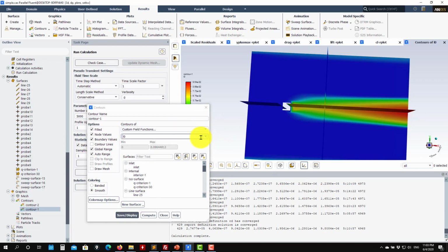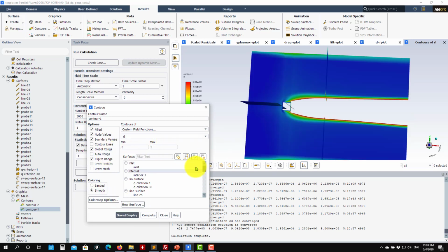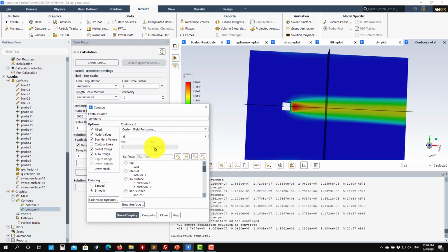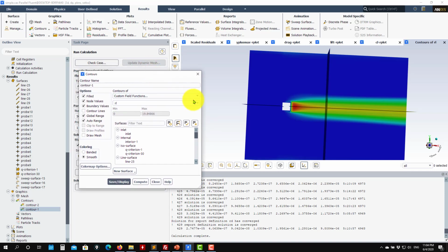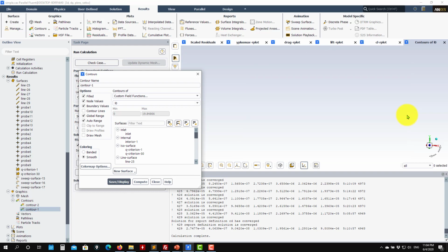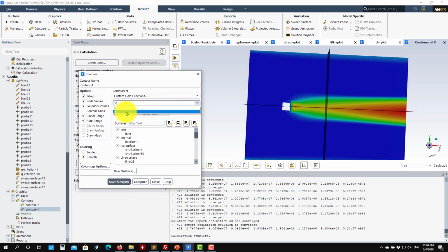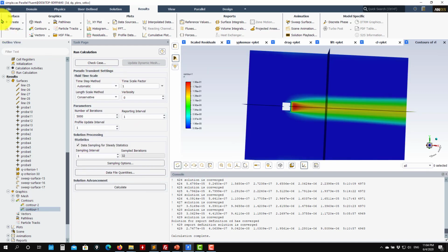So our integral length scales, and then we go RL and outer range. And as you recall the previous mesh, you will see that this probably is much better. Okay, the RL limits, let me erase this one. It was up to 8, I recall, or 10. Look here that we have larger values. Okay, it's telling me that we have much better resolution in many areas. And the integral length scales, well, pretty much the same as they should be. Okay, so this is our coupled solver.